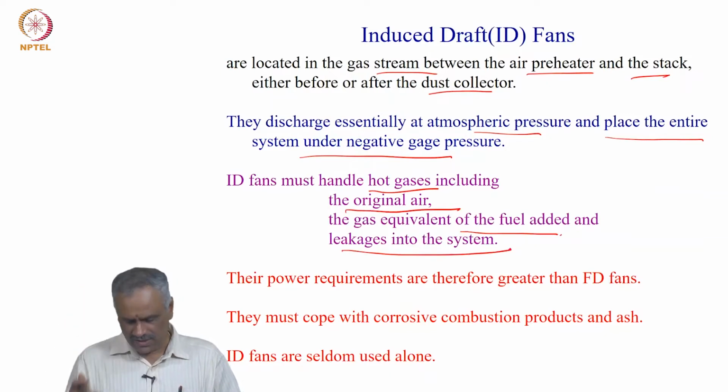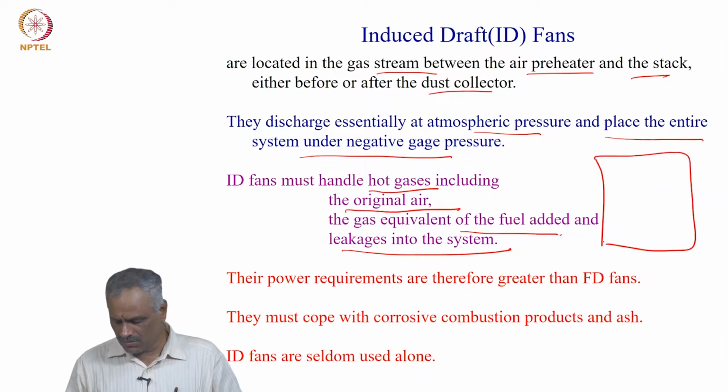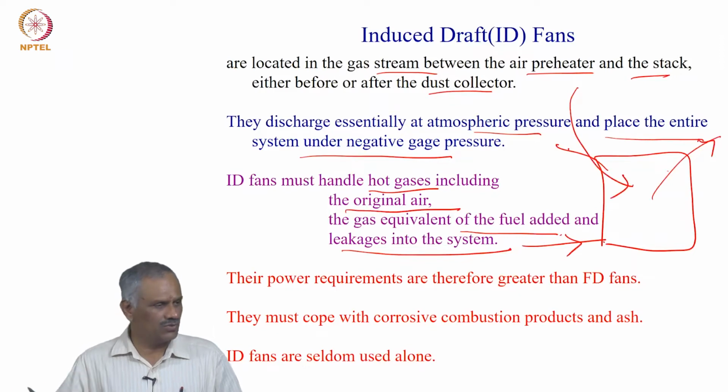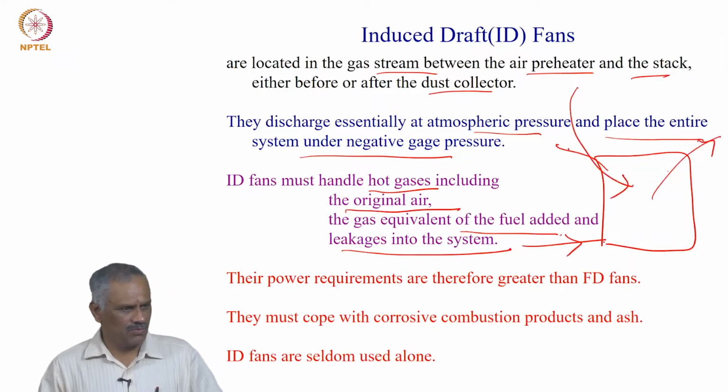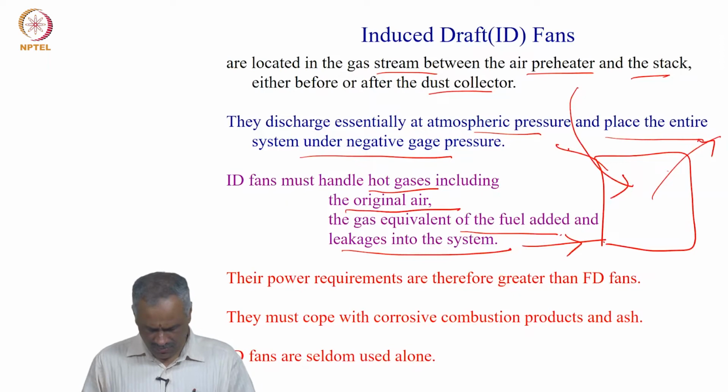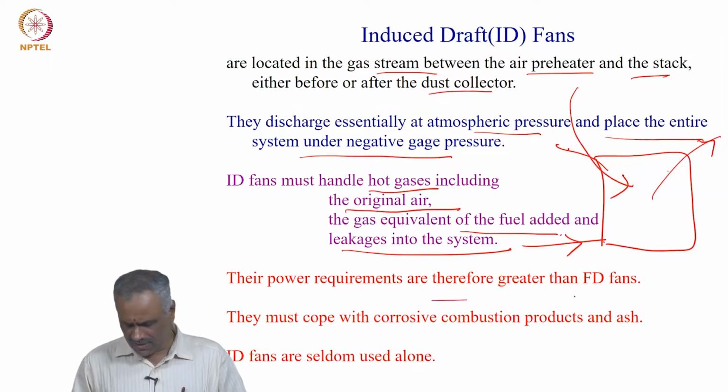So, there are leakages into the system. See, the problem here is that when you force the air, there is a possibility of leakage. If you are creating suction, the atmospheric air also enters inside, so there is a problem either way. Also, the power required for this is very high as compared to the forced draft,